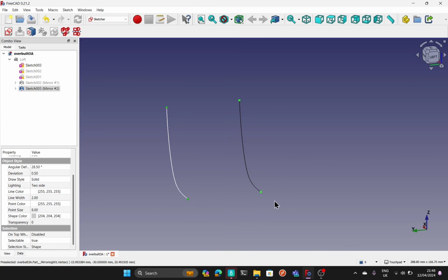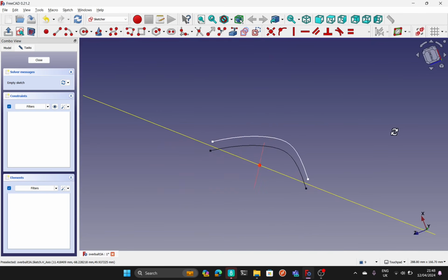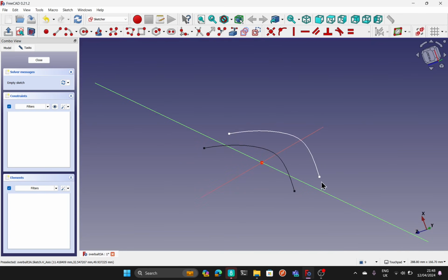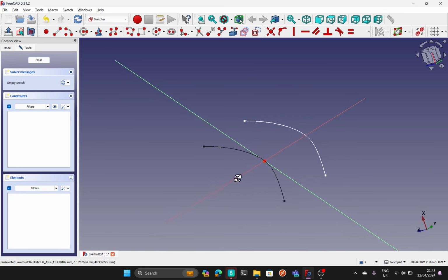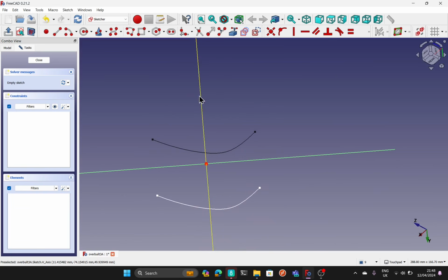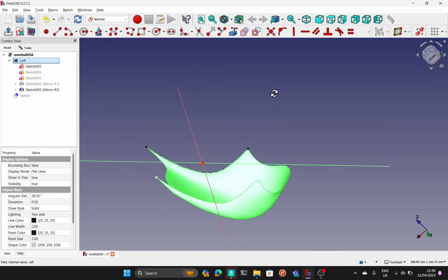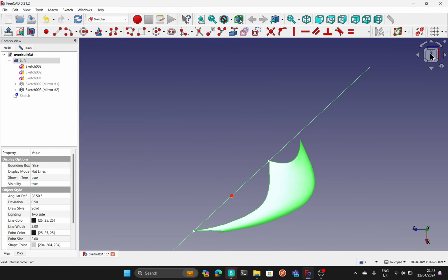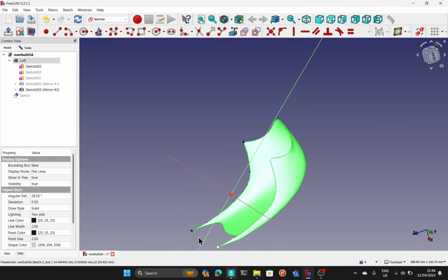With those 4 vertices selected, I'll create a sketch. What's happened is the sketch, if we look, has been laid across these vertices, like so. So if we think about, let's bring this around this way. Go back to the model and the loft, and we look at how that's been projected, you can see that the sketch sits planar to these points.